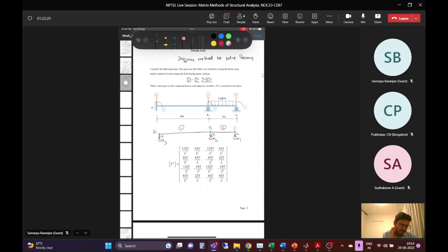Fortunately, the beam problem is not so big, not so tedious, because there is no concept of transformation matrix. There is only one matrix in the beam problem, and that is the stiffness matrix. Now, why there is no transformation, I think that is clear, right? Global axis and local axis are the same. Exactly. There is only one line of beam that is going. There are no members moving out here and there. So the global axis and local axis are the same.